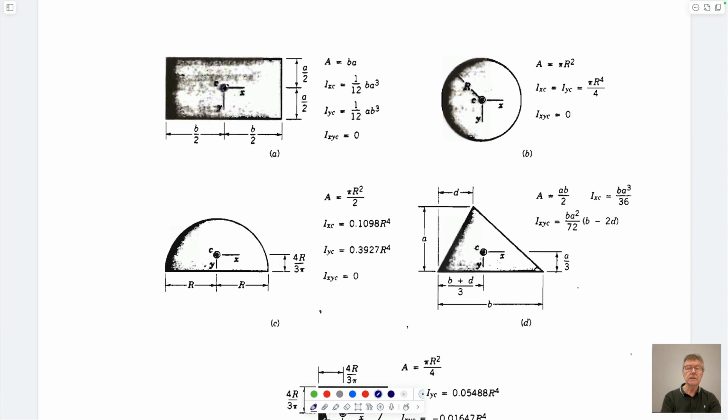For the geometry we looked at here, this is the centroid. I didn't crease this one. Remember what we did last time? The center of gravity of this piece of paper is just here, and this is the centroid, the balance point. And this is B, and this is A. And the second moment of area about the centroid is a half B A cubed.